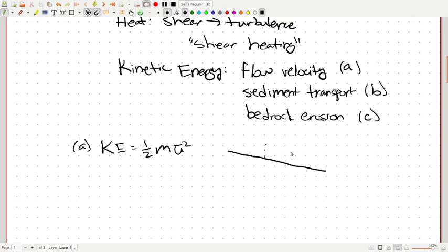And so if we have our little section of channel right here, and some sort of flow in and some sort of flow out, over a short reach of channel, the velocity and the mass, so I'm going to call it rho v, of fluid are actually not really changing, right? There aren't new tributaries coming in, so the volume is staying the same.